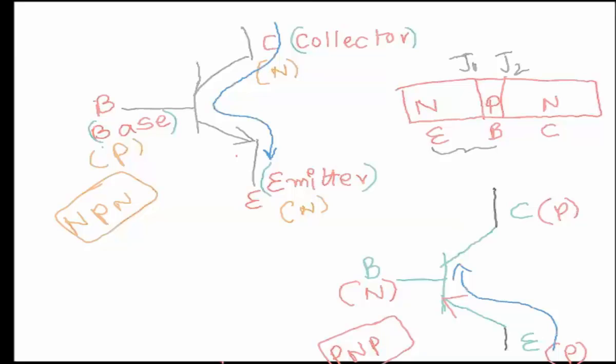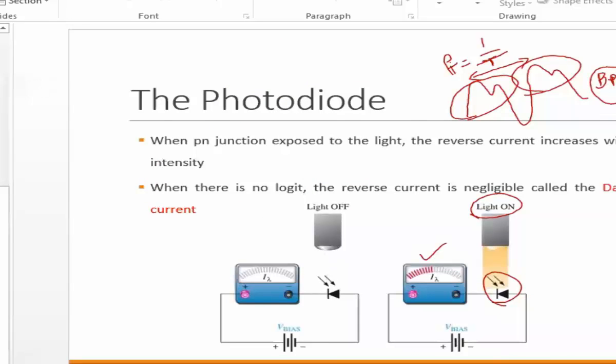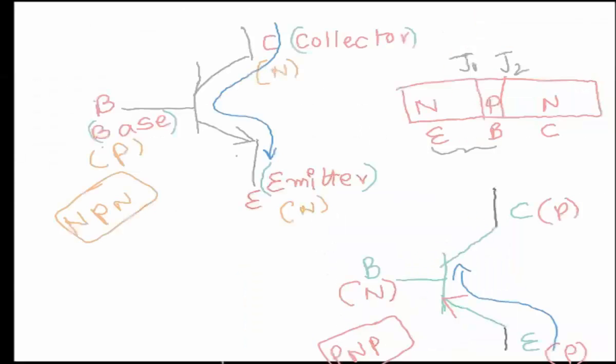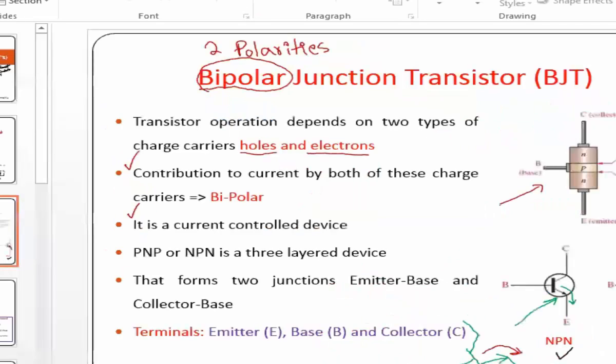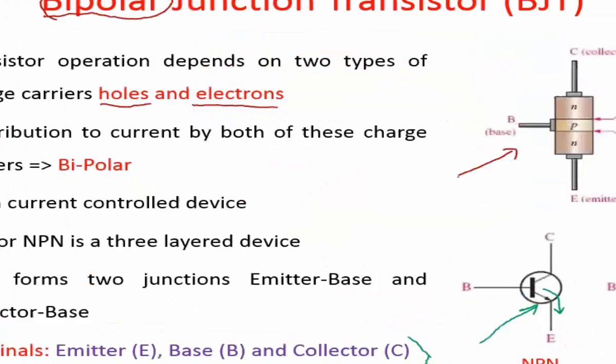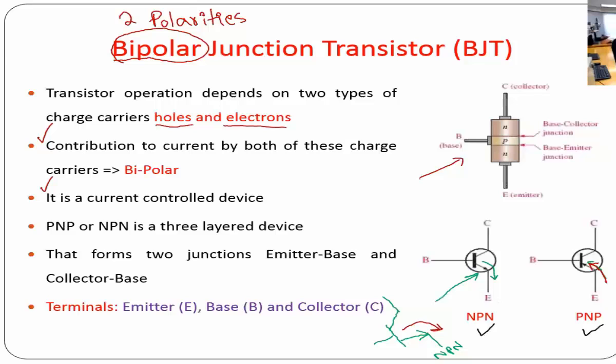That's why the arrows were pointed accordingly. For the emitter of an NPN, the current is leaving. For a PNP, the current is entering the emitter. But let's take a look at how this operates under the influence of voltages. Again, a base signal must be applied in order to even have a current.